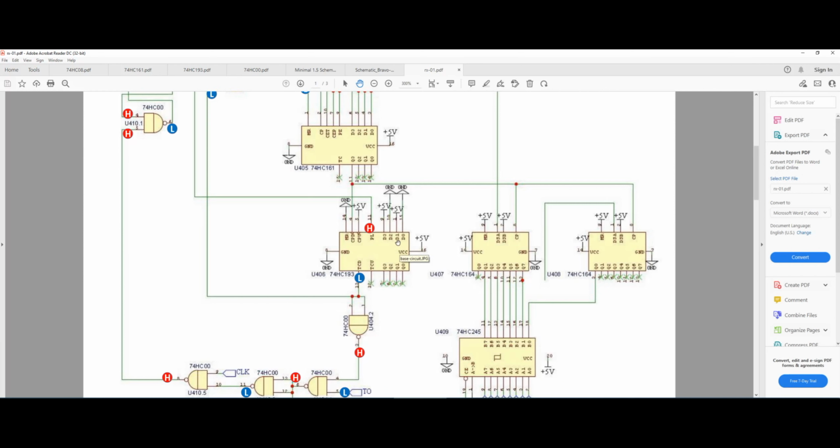So let's go back to that one more time. When we have an input set to a specific value, and we pulse the chip, it will be counting down from that value to 0. However, for the duration of that count, it keeps the TCD line, or the count down line, high.